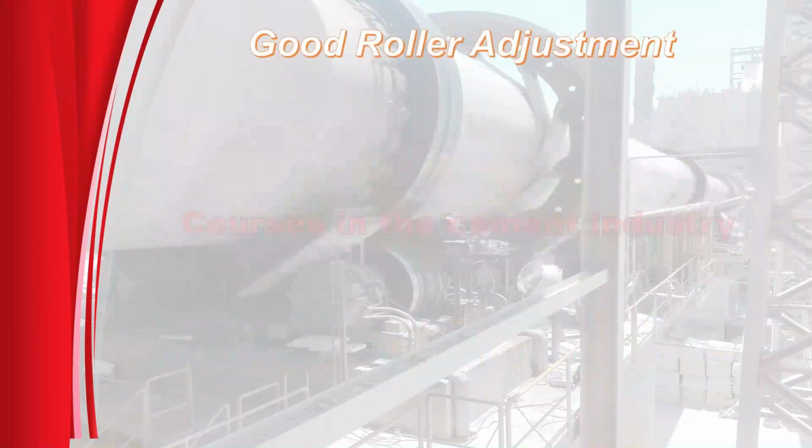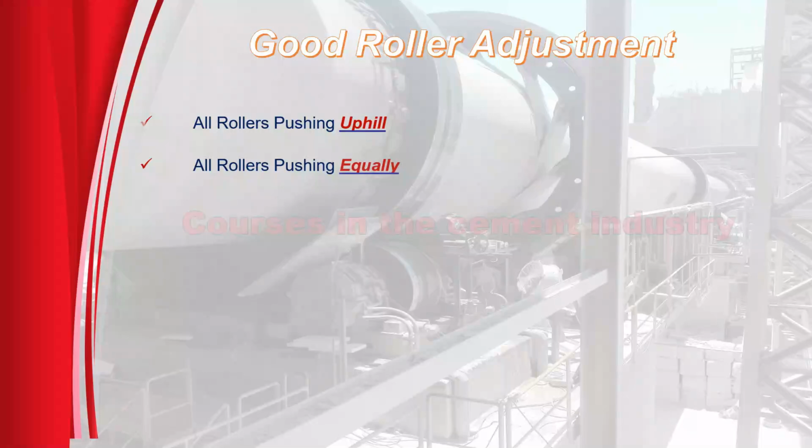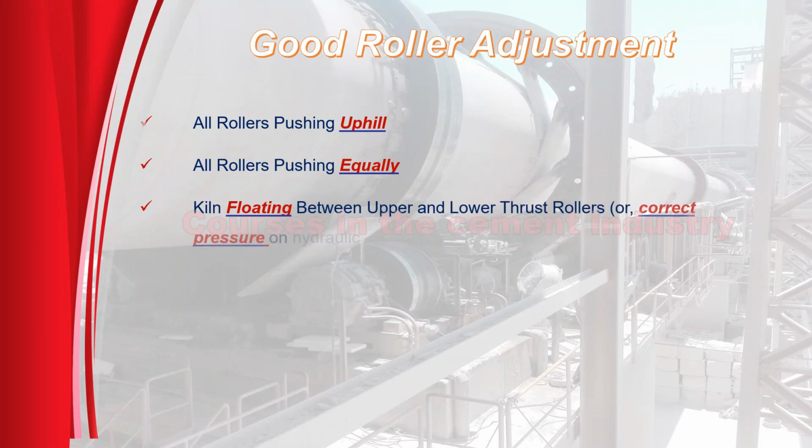Good roller adjustment: 1. All rollers pushing uphill. 2. All rollers pushing equally. 3. Kiln floating between upper and lower thrust rollers, or correct pressure on the hydraulic thrust cylinder.